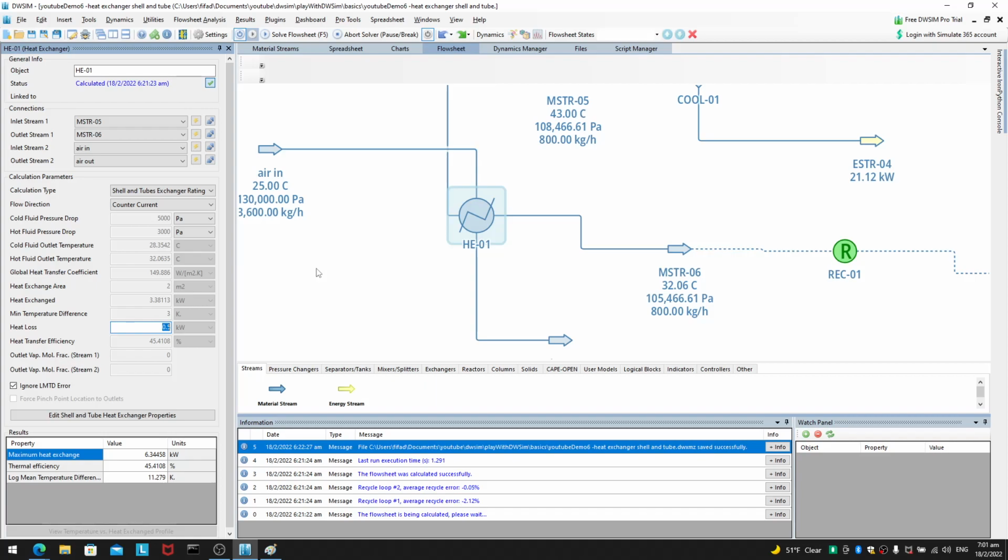Unless you put a lot of insulation, you assume there's a lot of insulation so that heat loss will be negligible, then all this manual calculation of heat loss to an environment, you should not have to worry about it. Right? So I guess the assumption here is that your shell and tube heat exchanger should be very well insulated, so that no matter what, your maximum or your minimum heat loss, it will be kind of negligible to your whole operation. So that's the idea here.